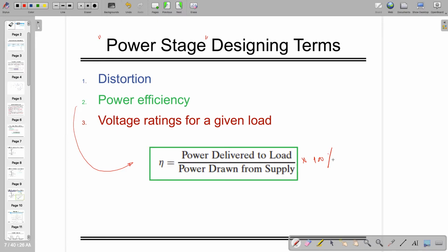It's not only the voltage which is required, but on top of that, the value of resistance which can be driven by the circuit has to be kept manageable, or the output resistance of such a circuit has to be much lower than what is required to be driven at the output side. So such things we need to take into account.